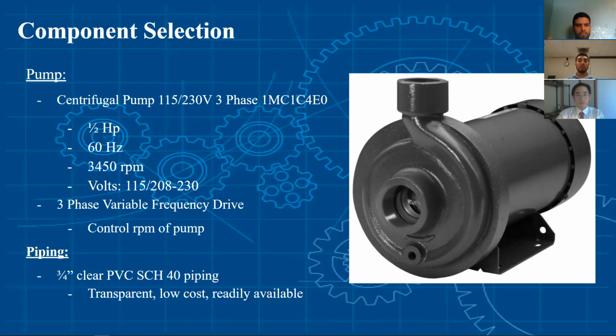Because the hydrocyclone must have a flow rate of 25 gallons per minute, the pump must be controlled by a variable frequency drive. The variable frequency drive would help us control the RPM that our pump would provide given our system's demand. This also gives the ability to test multiple different speeds and adjust accordingly to try and increase the separation efficiency of our hydrocyclone.